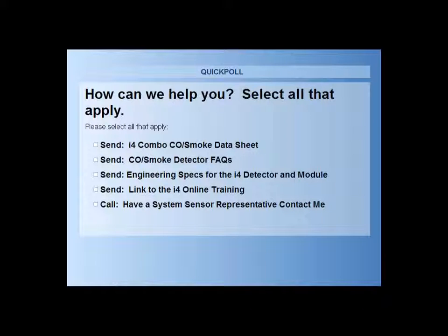I'll take that one, David. The testing agent that should be used to functionally test the CO cell itself is Solo C6 brand canned CO. That is what is listed with agency, so that's why you would want to use that Solo C6 brand.